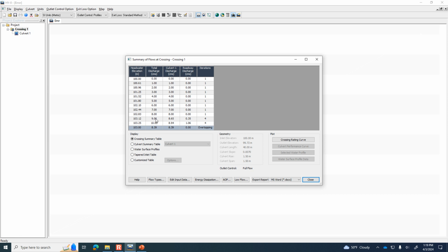What we'll do next, we'll say focus in on 5 cubic meters per second as the minimum flow rate, 6 cubic meters per second as the maximum, and then that'll give us a lot more precision in elevations to really hone in on what's happening at 2 meters.